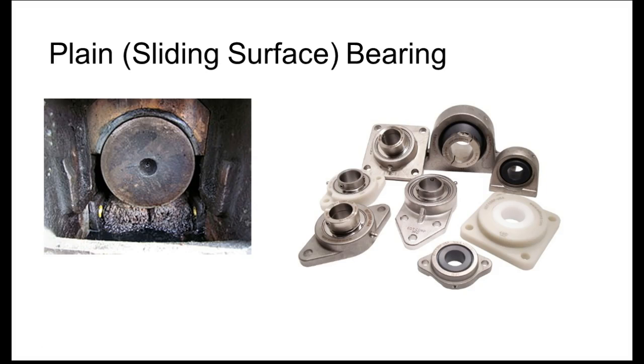All it is is two surfaces going together, but what you see is they have a slot in the middle of one of them. They're made out of Teflon, or metal, with slots on them. Notice it has what? A grease fitting. These are used a lot inside your HVAC system. So if you ever see a little grease hole, what you probably need to do once a year is drop a little oil down, not grease.